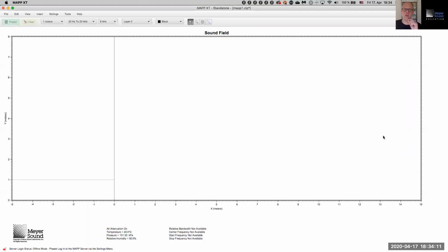So if I now press OK and nothing happens, then either I made an operating error, or not. I did it right. So there we have the line. This is my first point, at 4, 4 XY coordinates. It is 5 meters long, and it's pointing, for you, in this direction. It's pointing 0 degrees. It is level.